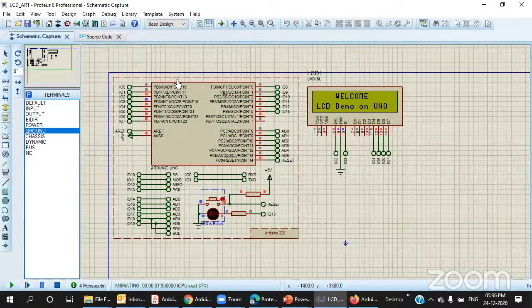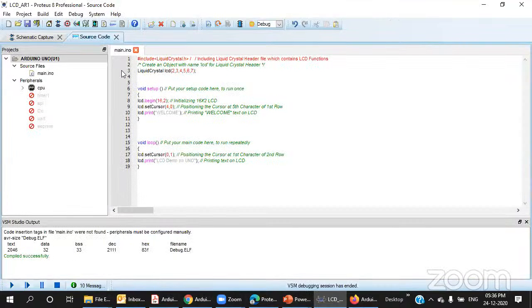Okay, this is the LCD. First, these are the basic functions, what I discussed. We need to add the header file, the LiquidCrystal header file. After adding the file, if you are using 4-bit mode, we need to use LiquidCrystal. If you want to enable RS also, it will help with that. For that, here we need to use extra values.